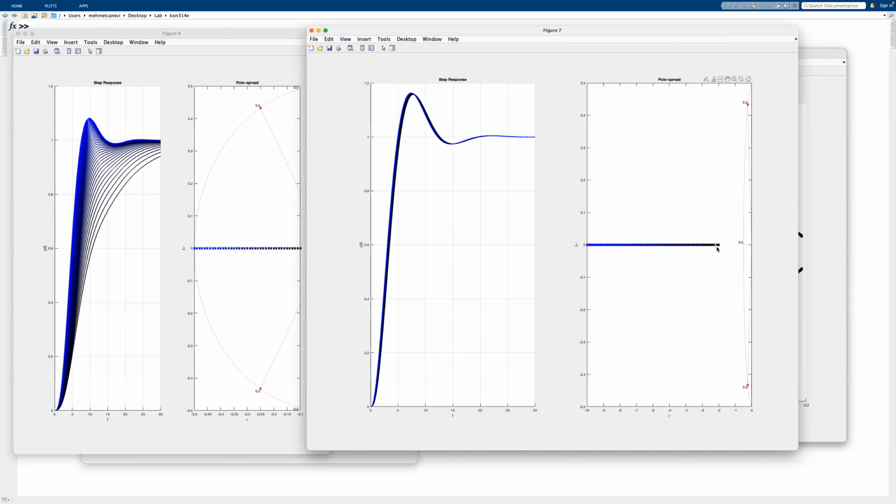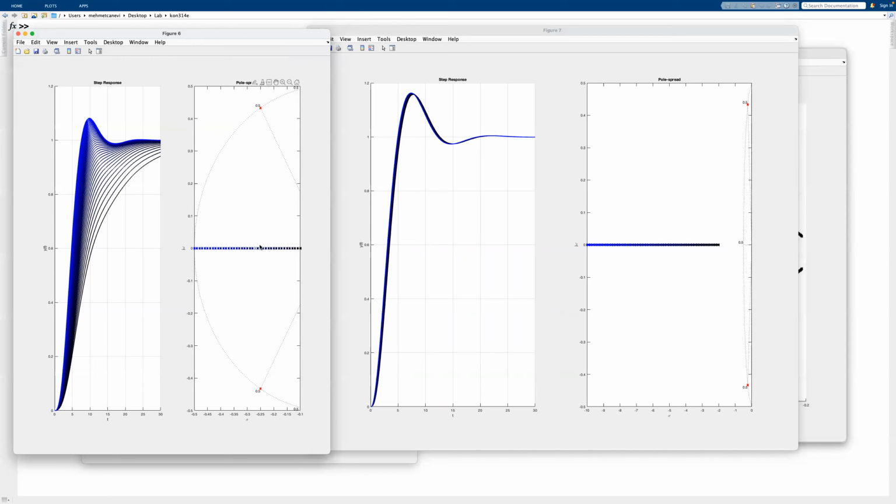That was the case last week, where we had like an 11 times factor, I guess, something along those lines, where K was 198, and then we had P at 11 while the real value of our dominant poles was like -1. So we had this nice behavior, and we matched our settling time requirement of 4 seconds last week for the P-type controller. This is the reason why, because if it's far away, the third pole doesn't really affect the system. But if it enters the zone, if it enters the dominant region, which is this region here, then it affects the system's behavior in terms of settling time, overshoot, everything changes.